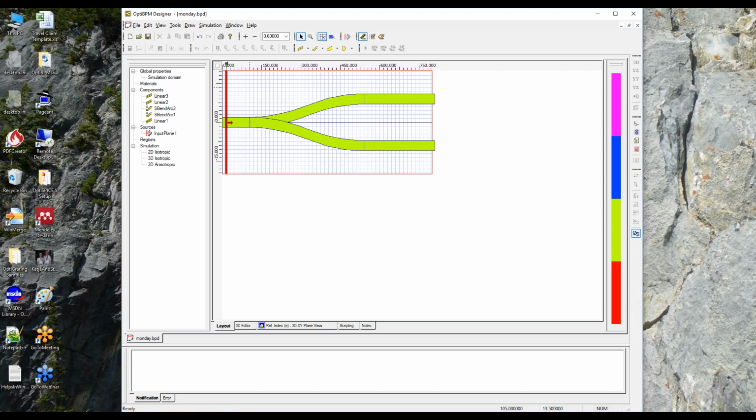I showed you about how the beam propagation method works. It works strictly from left to right, and from that you might be able to guess that it's not going to do reflections, and that is connected to refractive index contrast. In plasma type materials, there's very large refractive index contrast, and usually that means that it's just outside the scope of the beam propagation method, especially if the contrast occurs in the direction of propagation. It's not to say that it can't be done. In fact, I did it once, but probably not. If you've got materials like that, you're probably looking at a finite difference time domain method as your method of choice.